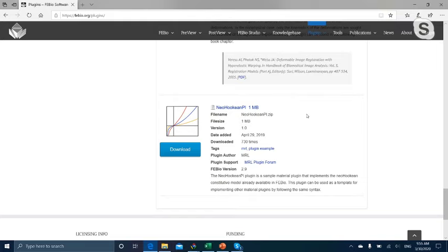Yeah, so for FSI, it's compatible with any hyperelastic solid model that's currently in FEBio and even a solid mixture. So you could include damage into your solid for FSI. What FSI does is that it makes sure that the solid domain knows what the stresses and pressures are from the fluid domain, so that it's able to calculate the damage properly. So yes, it is possible in FSI to include damage into the surrounding solid.